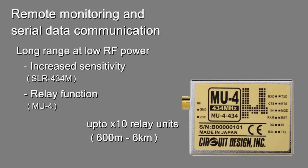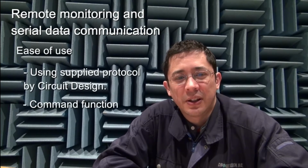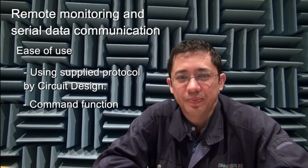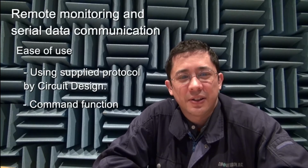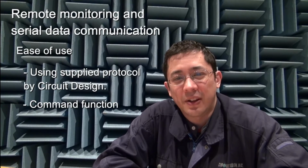To ease development efforts, circuit design MU4 and SLR434M implement a command system to handle the transmission of byte data. The command protocol allows the user to do other extra functions such as remote RSSI inquiry, route messages around networks, configure user IDs, for example in a sensor network. Note that users that would like to implement their own protocol can do so on the MU4 and on other modules.